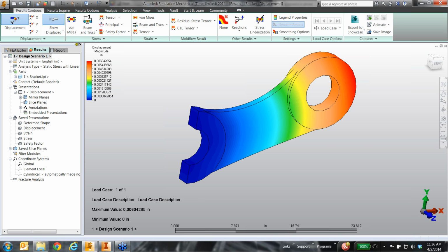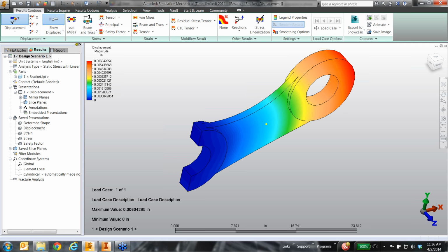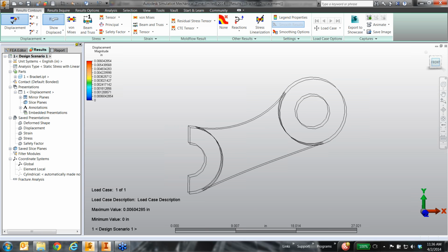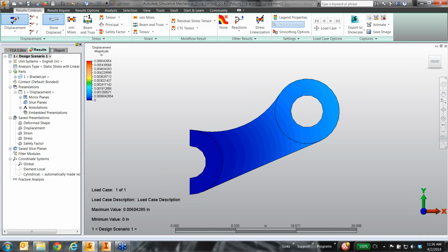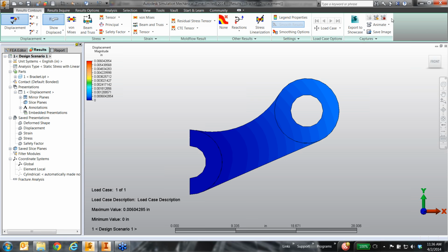It's pretty quick here. So that first inspection, displacement, 0.006 inches. So I mean, that's kind of what I expect. I forgot to show you that this is a 1-inch thick plate here. So it's a pretty beefy plate here. So a lot of this with analysis, anybody that does these, you can kind of see, let's make sure it animates fine. It looks like I would expect in there.